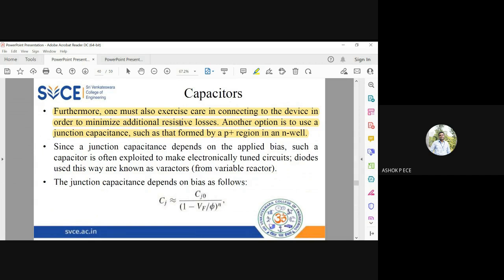Okay. And in case you cannot use the capacitors from all the methods discussed previously, you can directly go for a varactor diode. A reverse biased diode can act like a variable capacitor. So varactor diodes are specifically meant for replacing capacitors, and you can see the reverse bias will determine the capacitance of your junction. So this is the formula you can see.